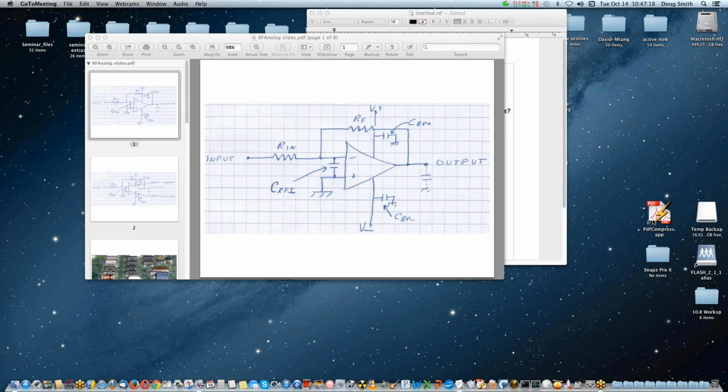Another question? Yep. How about what influence the capacitive load in your sketch would have on 2 gigahertz rectification? You mean like this little guy here, for RFI? It tends to kill it because it's rectification at the input that causes the most problem, because it's like a little crystal radio. Some PN junction, which may not be very good at 2 gigahertz, is good enough to create a rectification, which creates even just millivolts of DC offset. If you've got a gain of 100 in this circuit and you create 2 millivolts of offset, you get a 200 millivolt offset at the output of the op amp, and then if it's modulated, now you've got that on top of it.